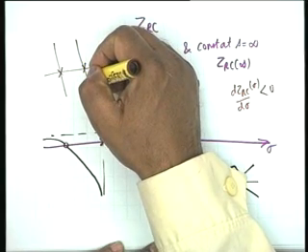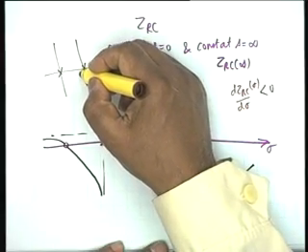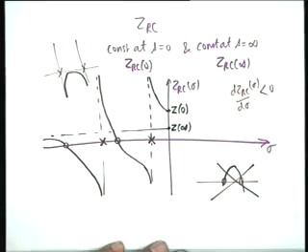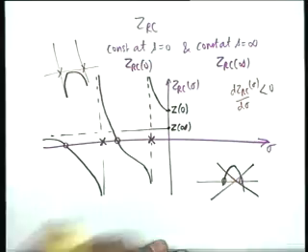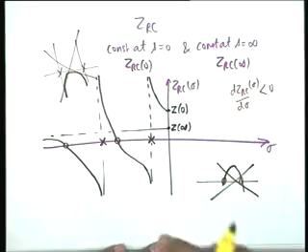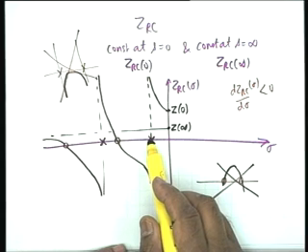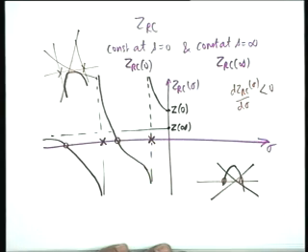Why not? What is happening? The slope has to be negative, so it must come down and then it must go like this. It must come up and then go without crossing a 0. So this is not permitted either. Number 1, poles and zeros must alternate. Number 2, observation: the first critical frequency has to be a pole.